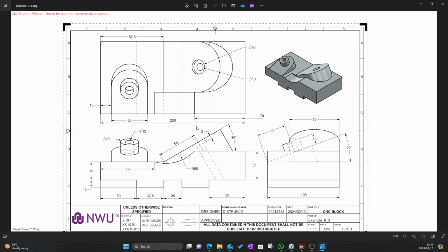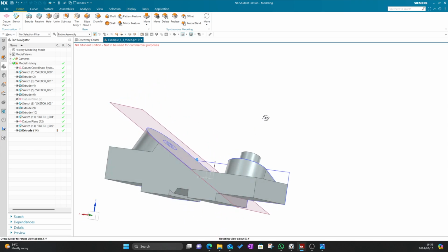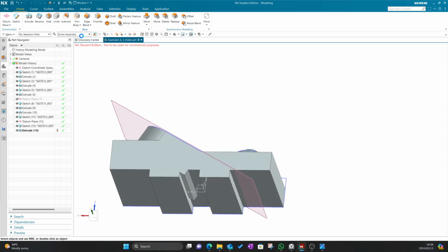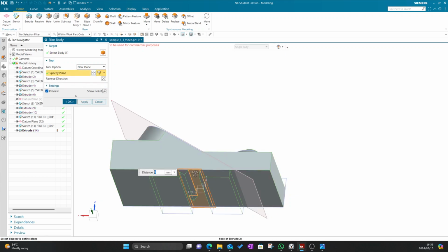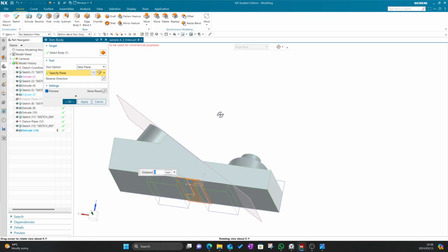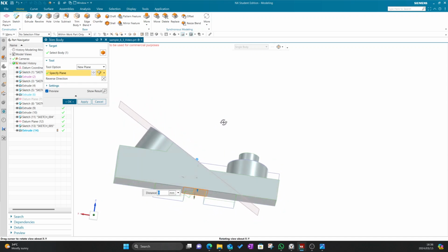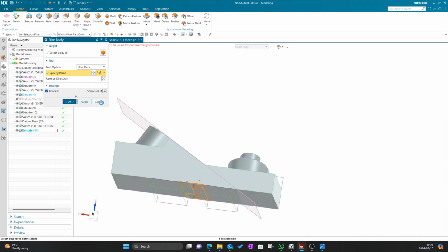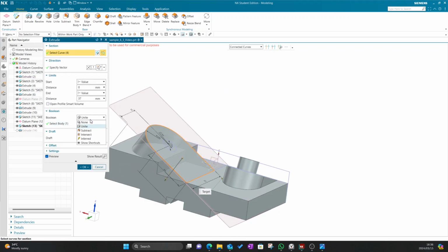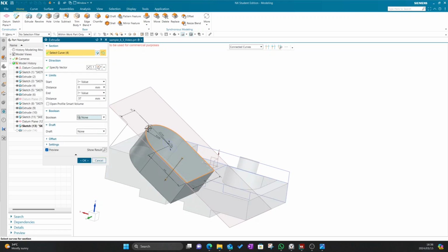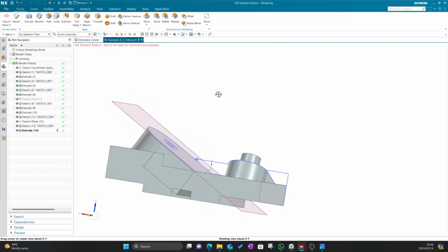Yeah, you'll see it's quite similar. So let's quickly trim that. So I'm going to trim the body. I want to trim that body on that plane. So you'll see it trims anything of the body below that plane. But the problem now is it also trims these steps, and I don't want that. So going back to my extrude function, I first want to create a non-Boolean operation. So it's a separate body inside that body now. So now it's two separate bodies, you'll see.